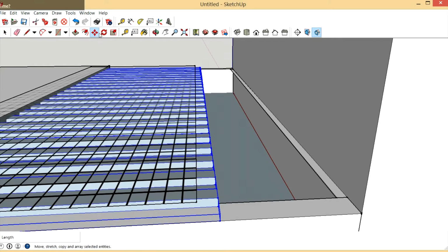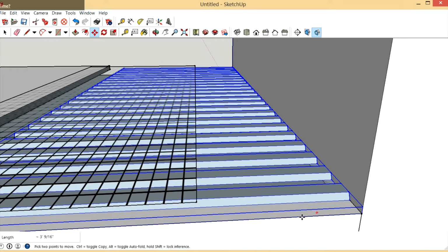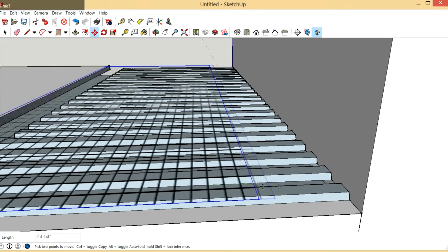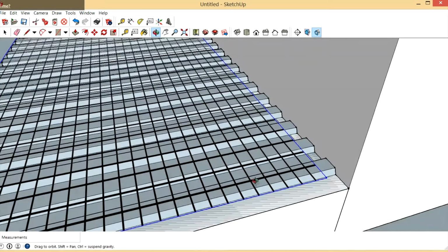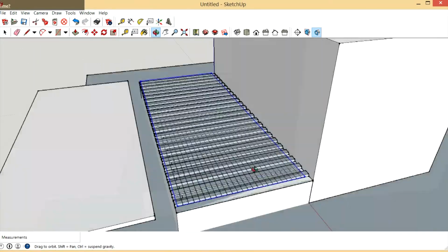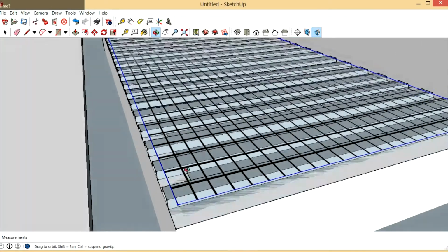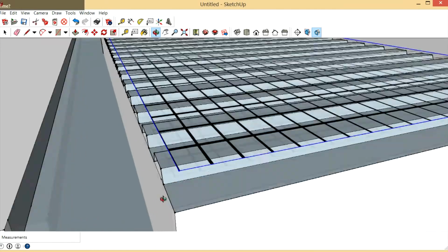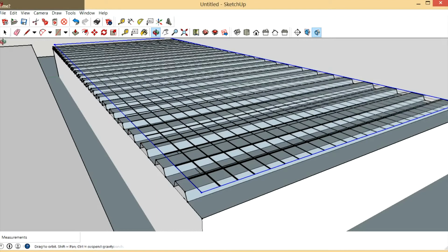over to that point, set it on top of that, and then you'd bring your wire mesh over. It would be in the concrete, but it would be hovering above the pan. And then you would pour your concrete over that. You'd still have a form around the edges, and you'd want this to be back.